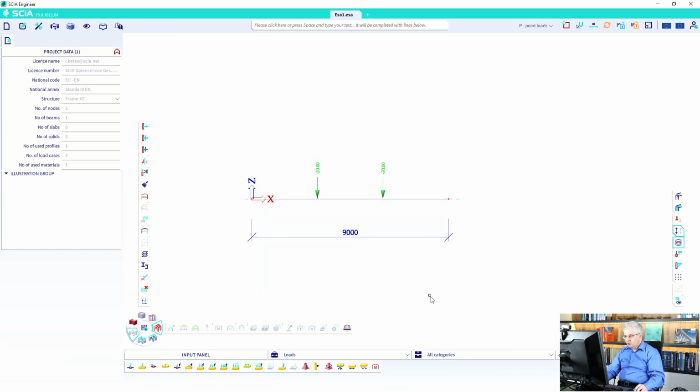So that's almost everything we need for standard structures. If you have such a simple structure like this one, where you have only one member or one column, then you have to define more finite elements, because one element means two nodes. Usually one of these nodes, for example for a column, is in the support. So you have only one node with one mass. So you can get one eigenform. And if you are in space, then two of them. But we need more of them. So therefore we have to create more finite elements on the members.